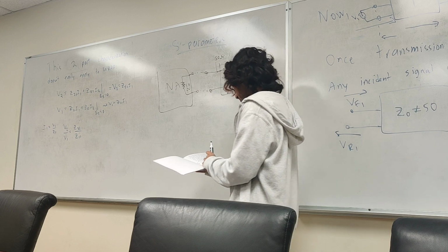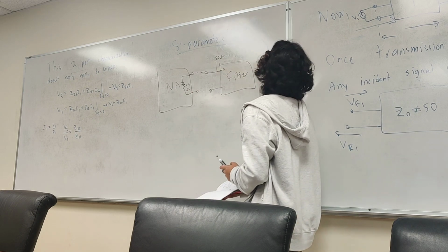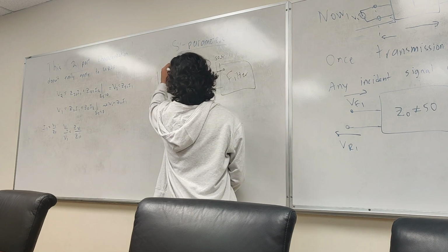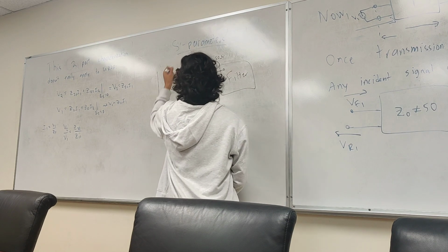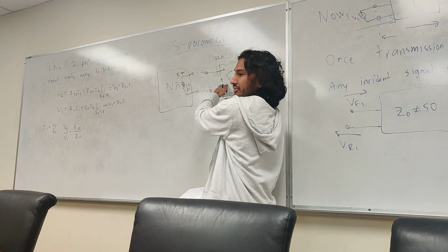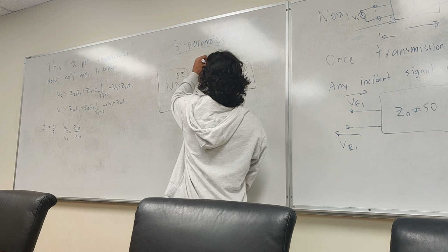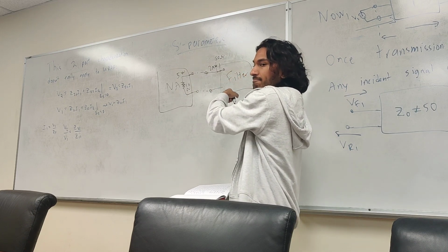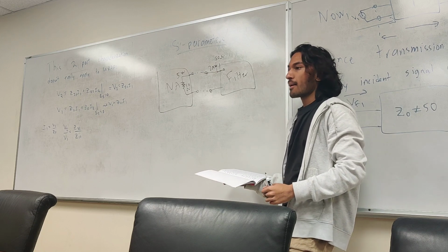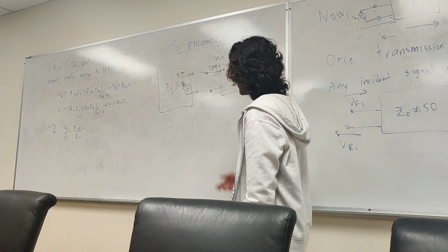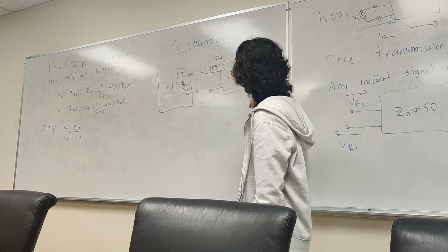The other thing is that this network analyzer does internal calibration, right? It's not going to be accurate numbers, but let's say this is 5 watts here. It's going to output some 5-watt signal. If this is truly 50 ohms and this is truly 50 ohms, 2.5 watts is going to get delivered into our filter. Everyone kind of follow that? There are a few textbooks that use this abstraction as well.